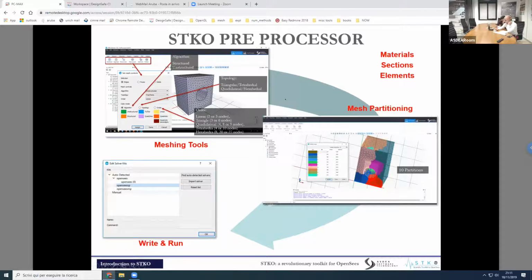Basically, as you know, we have three kinds of versions of OpenSees: the sequential one and two that are parallel, the OpenSees SP and OpenSees NP. Now, typically, people use OpenSees SP to run large models, while OpenSees NP is used to run parametric studies. But actually, they do so just because writing TCL files for OpenSees NP for a single large model is not so easy, because you need to have those TCL files already partitioned. And this is not so easy to do by hand.